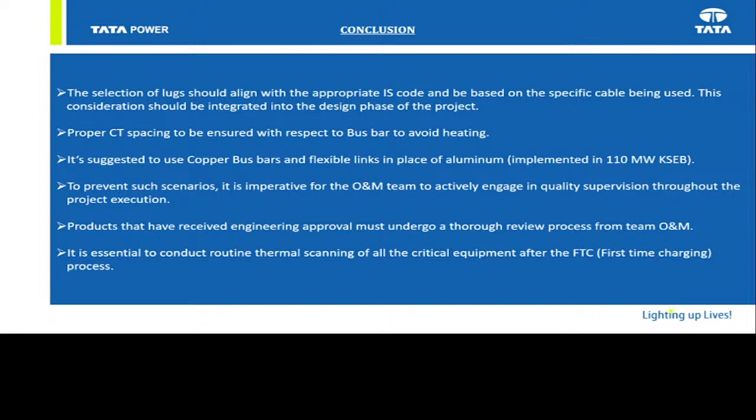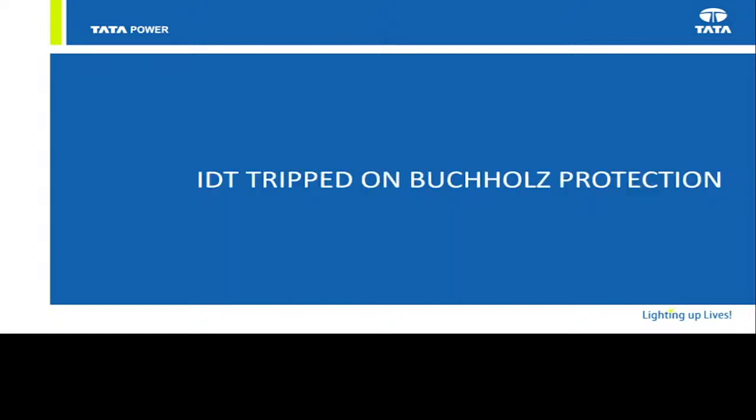Then proper spacing of the CTs, because the CT was very near to the bus. And then one recommendation was that at this place, at the current collection, it is better if we can use copper material, but because of cost, if we are using aluminum material, we have to take a lot of care with engineering and quality. That's it from my side.